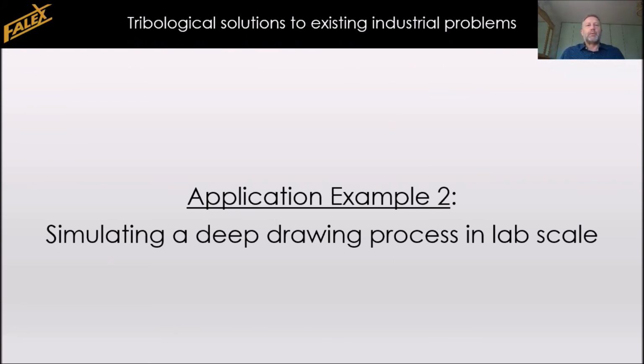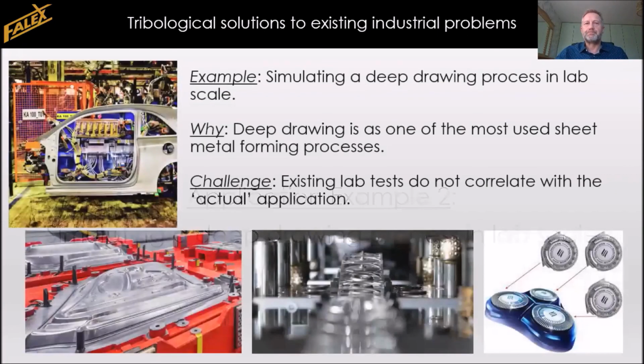In this example, we approached the challenge of simulating a deep drawing process on the laboratory scale. So deep drawing is a process that's been used extensively in the industry to form all kinds of components, going from large scale automotive to smaller components in consumer products. And the challenge exists that it is difficult to simulate the forming or the friction in the forming process on the lab scale.